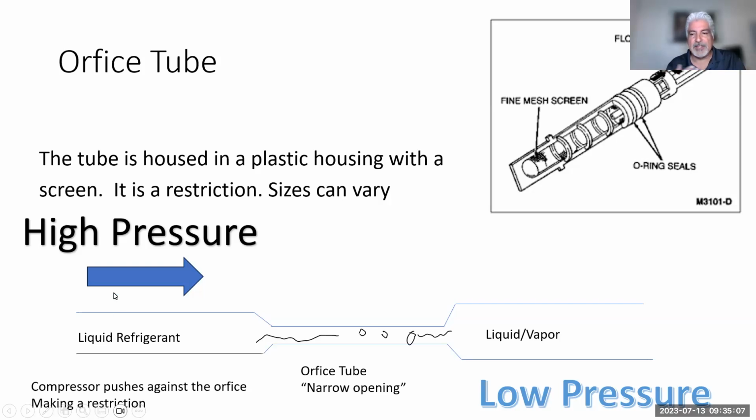Since I talk about my vehicles and other customer vehicles too, when I drive a 6.4 or a 6.7, that viscous fan clutch, I could actually see that fan turn on and you could watch that high side gauge drop a little bit. And it's normal because those trucks just move air. And in this case, since they're moving air across there, it does cool down that condenser very quick. So it works much more efficiently. So therefore, it definitely does help.